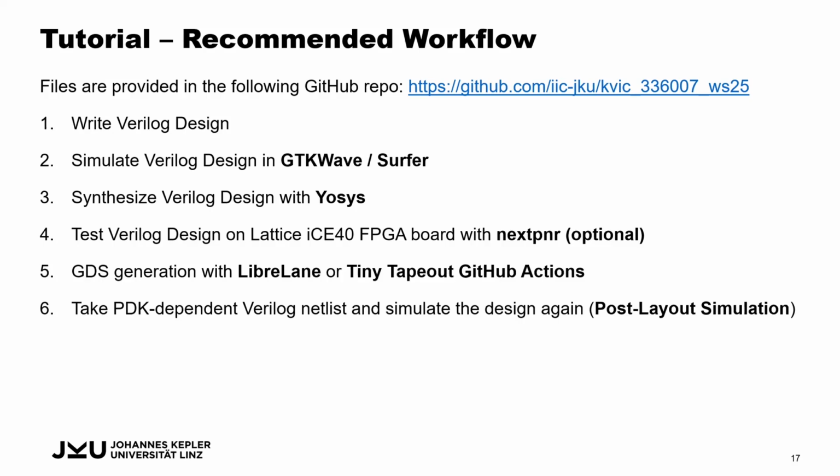This is especially interesting for beginners, because some beginners have a software programming background and then they want to divide, for example, something. And as you probably know, in digital design, a division is really complex. So normally you use shift operators or a CORDIC IP.